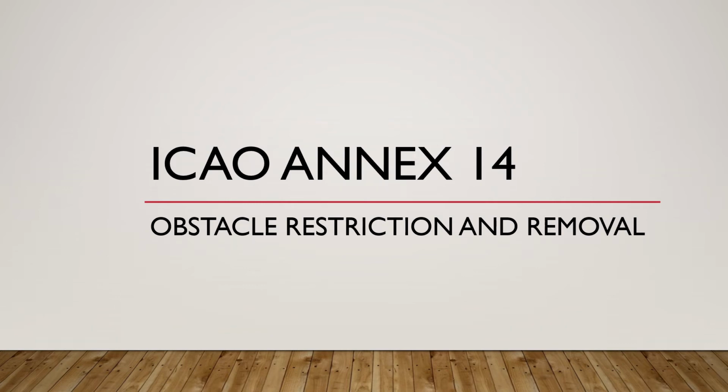An airport plays a very important role in the economic development of the country. In regards to this, it is important that the airport becomes usable and is free from obstacles from the point of view of operation of the aircraft. So here in this presentation, we are going to learn about the standards and recommended practices of ICAO Annex 14, in a chapter which deals with obstacle restriction and removal. So let's move towards learning how these surfaces are defined.